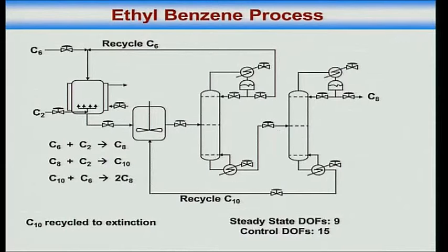If you allow your diethyl benzene to build up in the bottom recycle loop to a sufficient extent such that its concentration goes up, then the second reaction rate will go up, and ultimately consumption by the last reaction will balance formation by the second reaction.